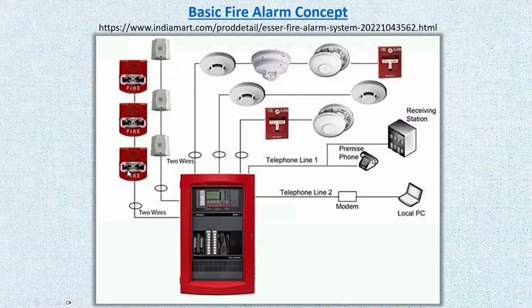Comparing to the security alarms, you can have a noisemaker, which is a siren. You can have a strobe light. You can have both siren and a strobe light, or you can have a silent alarm. Now, when it comes to fire alarm, you have to have the annunciator that is supposed to produce a certain type of noise, and it's supposed to do the strobe light flashing.